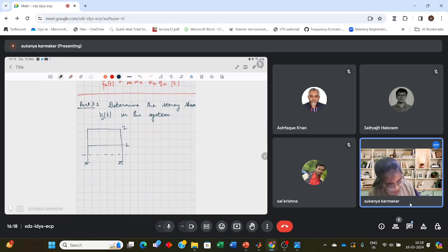In this floor, what is the shear? Let me write it as V_1n as a function of time. It will be the stiffness of this floor, k1, into the motion here, which is u_1(t). What is shear? Basically, what is this lateral force? It will be the stiffness into the story drift or deformation. Since here the bottom is fixed and this part is moving, you have u_1(t).